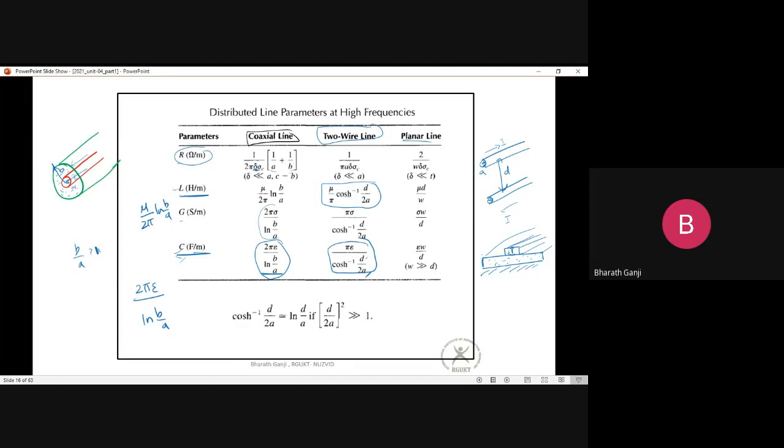Until we see what transmission line theory says, I cannot tell you what its advantage is. But right now what I can tell you is it will definitely not neglect the transit time effect. It will include it and give you a good and correct approximation for your circuit behavior. And to do that, we first have to work out transmission line theory. If I take any kind of wires, first of all, I need these 4 parameters: resistance per unit length, inductance per unit length, capacitance per unit length, and conductance per unit length. I need to calculate these parameters beforehand.